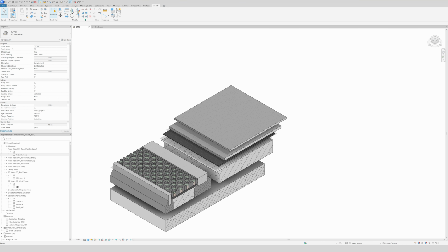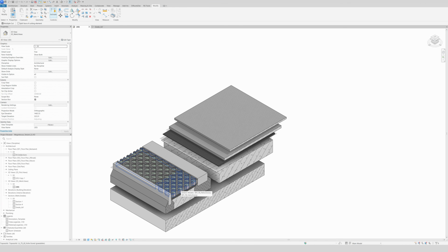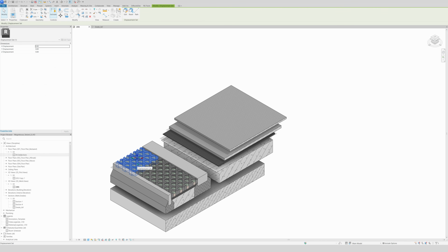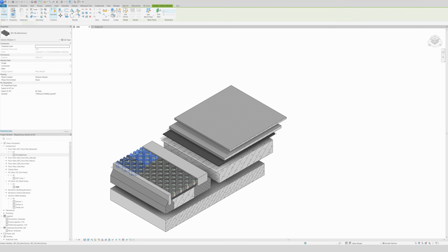So to modify, we go to the cut tool, make sure multiple cut is on, and then we're gonna use the top of solid, and oh, again I missed one right here. Those need to reset because I can't cut them, and then like here, voila.